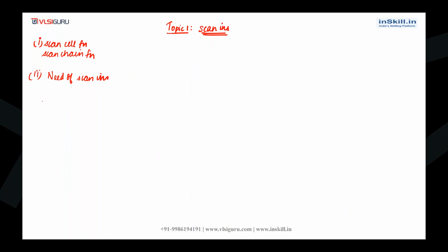Then, what is scan insertion? Scan insertion means all the normal flops will be converted to scan flops. If a normal flop has to be converted to a scan flop, then it has to pass certain rules.